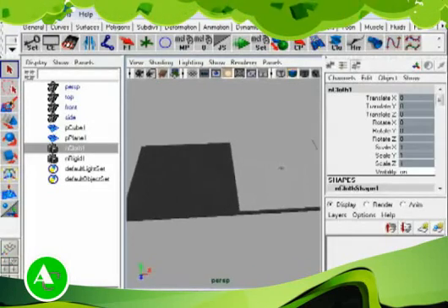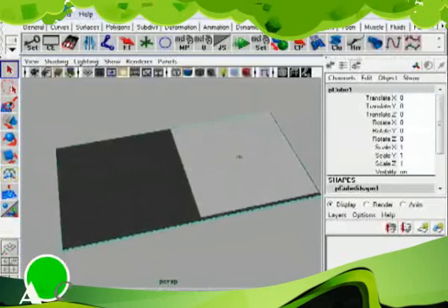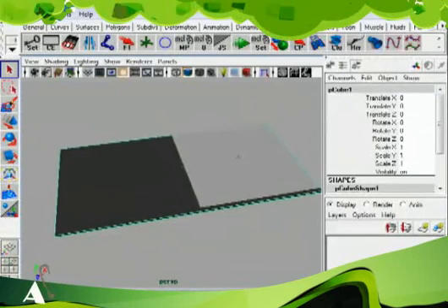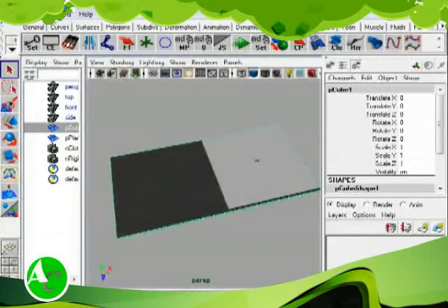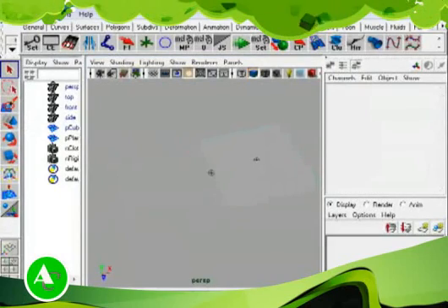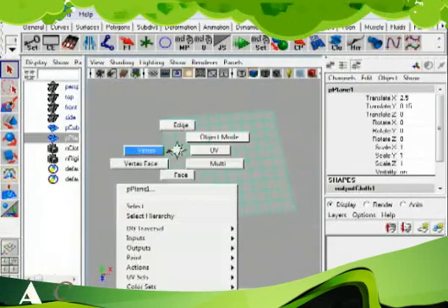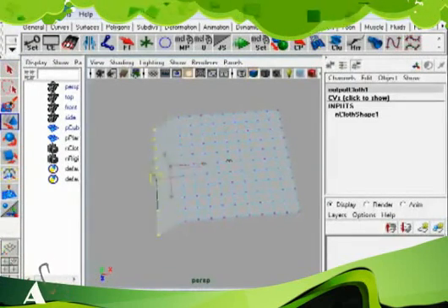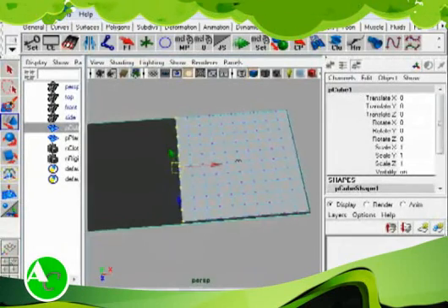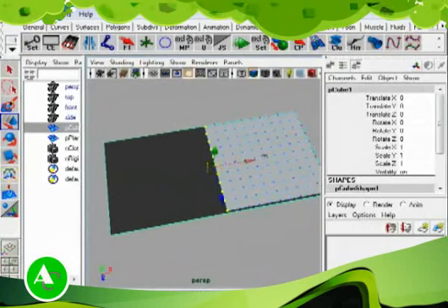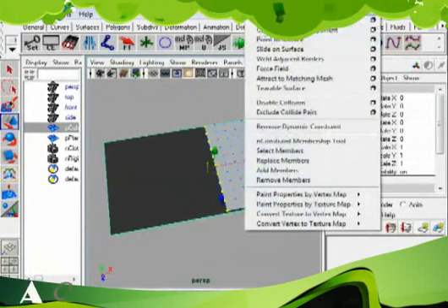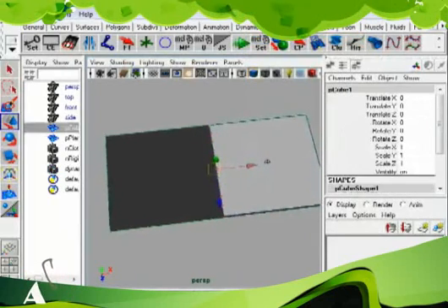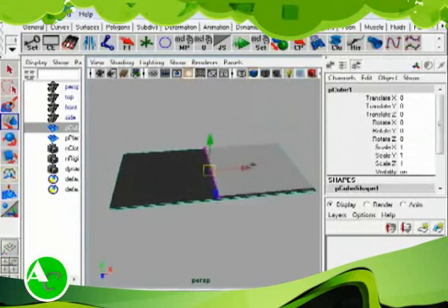Basically what we need to do now is weld the piece of paper on top of this geometry, the book. To do that, we can use the power of Maya's constraints. Let me quickly hide the book, and I can select the piece of paper and select its vertices. I'm going to select the vertices on these sides, and then shift select the cube, that means the book cover, and then I'm going to use an nConstraint point to surface. Once that has been done, the paper is constrained to the book, like welded. You can see it in action if you hit the interactive playback on.